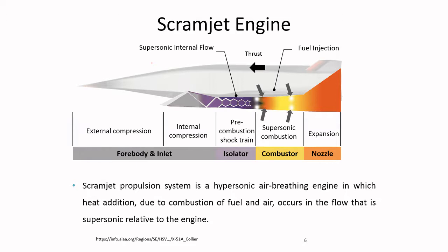The shock angles will be quite narrow, and that calls for this very sharp cone at the inlet. You will see that the shocks will form like this, and this part will also compress the airflow, and this part will be characterized by external compression.